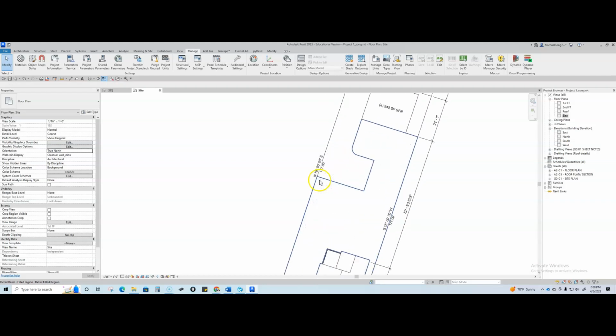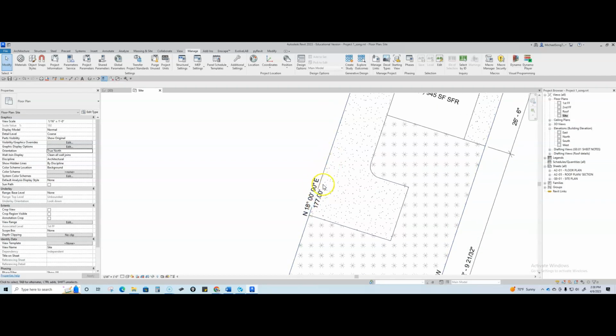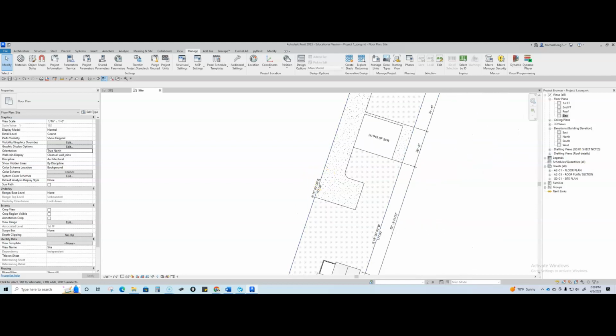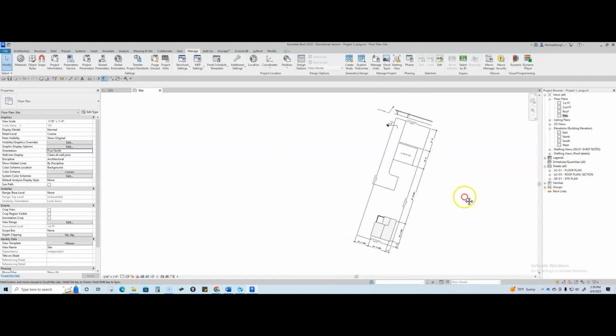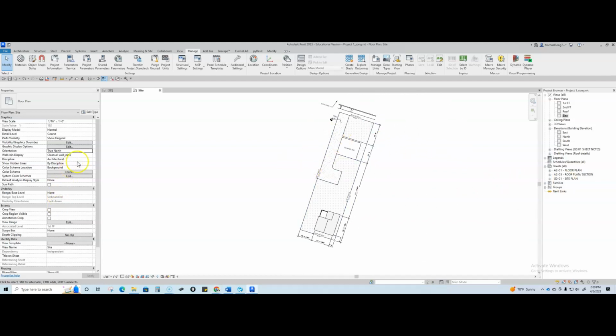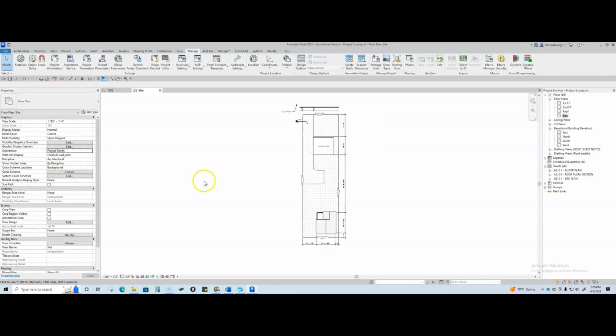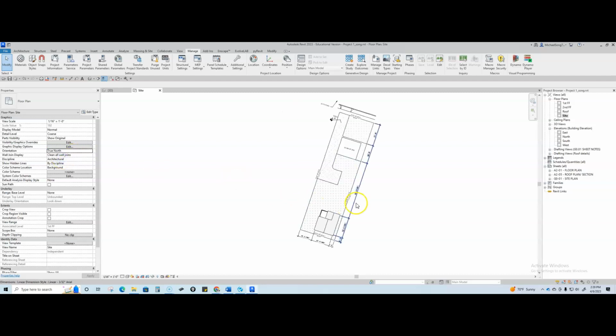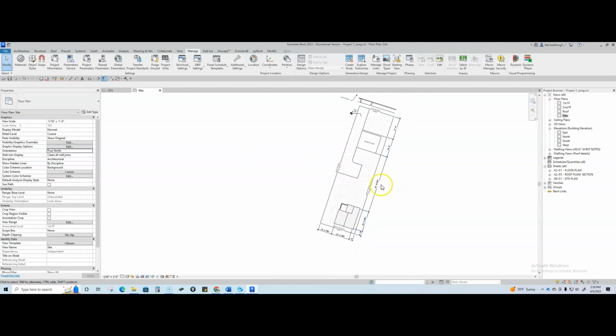And what's really cool is that Revit already knows that this line lives 18 degrees rotated from north. So it's very intelligent, that's what happens when you have a tag and you model everything physically. So that's how you rotate to true north. And obviously when you're drawing, you want to have it at project north so that everything's upright, if you will. And then when you place it on your site plan, you want it at true north. I mean, actually, this isn't too bad. We can probably continue to work on this just using the true north view.